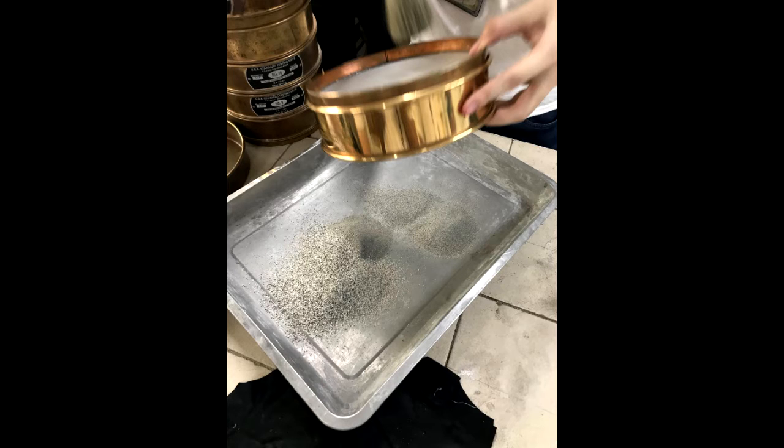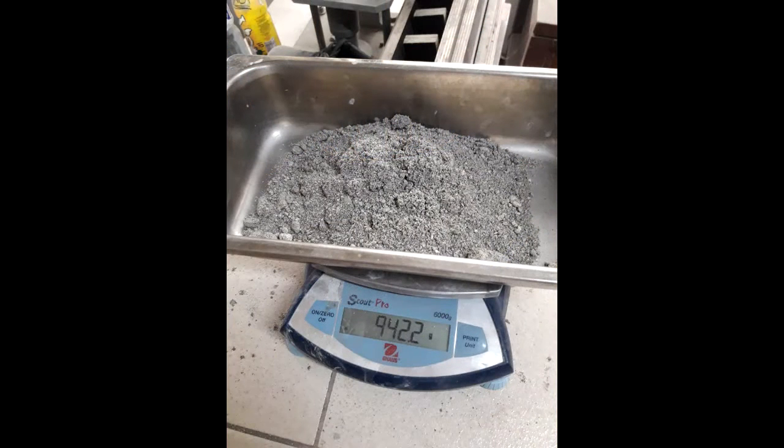Established values: fineness modulus 2.3 to 3.1. Max size of the coarse aggregates 37.5 to 9.5 mm. Absorption 0 to 8%. Bulk specific gravity 2.3 to 2.9. Surface moisture content for the coarse aggregates it was 0 to 2%. For the fine aggregates 0 to 10%.